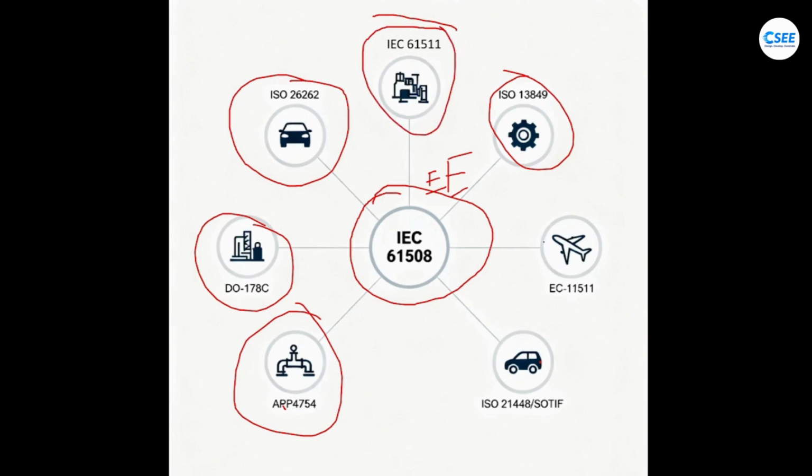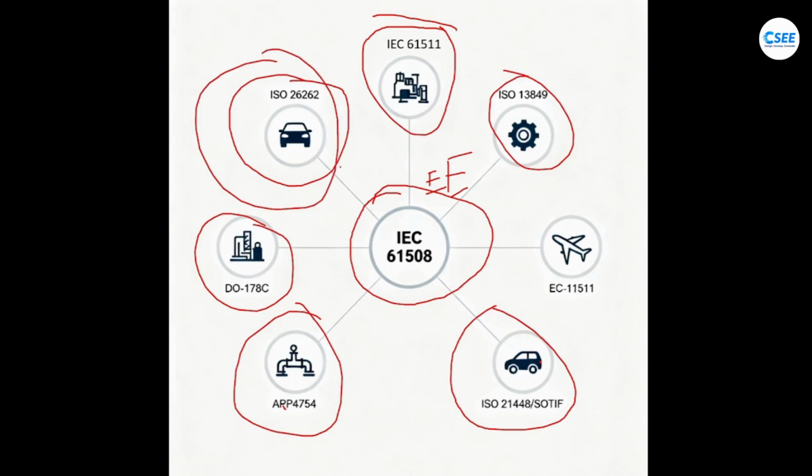And for autonomous driving systems, a newer standard called ISO 21448, also known as SOTIF, Safety of Intended Function, deals with the risk not caused by failures but by system limitations. One key part of ISO 26262 is the concept of ASIL, or Automotive Safety Integrity Level. We will discuss this next because it's critical to understanding functional safety in cars.